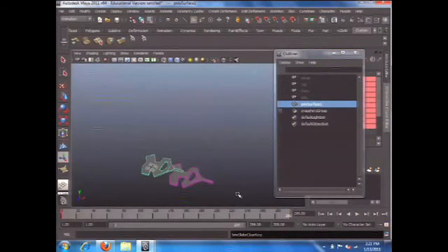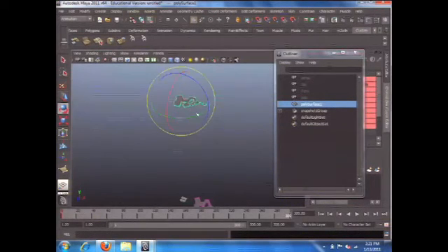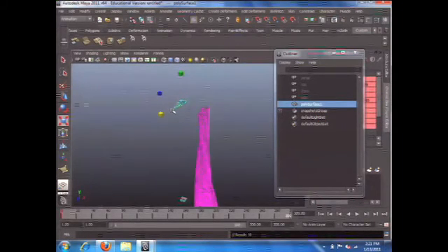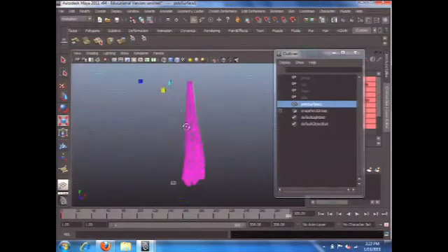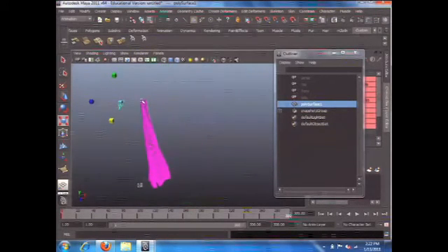All right, so if I delete all the keyframes except the first one, you'll see the animation is broken. So I have to set it up again. One more time, here I'm going to move, rotate, scale, S, keyframe. As soon as you do that, your keyframe is coming back. All right, really cool stuff about the conceptual model. This technique, you can definitely use not necessarily in polygons. You can use it for NURBS as well.